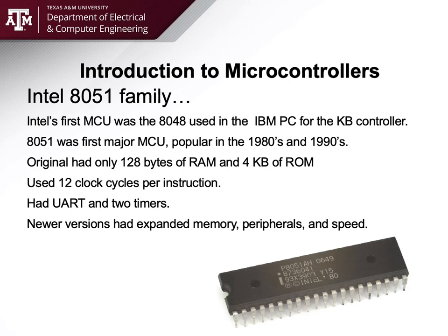So you had one little microcontroller that just monitored all of these I/O pins, doing row column switching. If you ever want to learn about that, please ask me. You energize a row to monitor a column, see if a key was pressed, and you can do quite a few keys with very few I/O lines by doing that. And that's what they actually did.